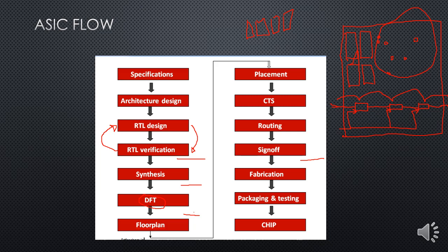We don't want any asynchronous signals or elements in my design, because with asynchronous signals, we cannot expect their functionality or behavior. If we have asynchronous signals, our life will become very complex, because we cannot deal with all the various kinds of asynchronous signals. It's not only one such path we have; we'll have multiple such things in my design. Dealing with all of them would be quite tough, and that's the reason we want everything in our design to be synchronous.